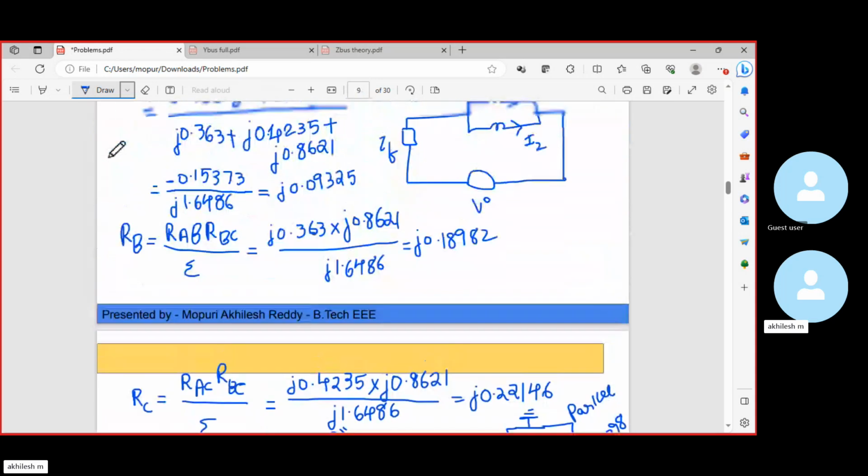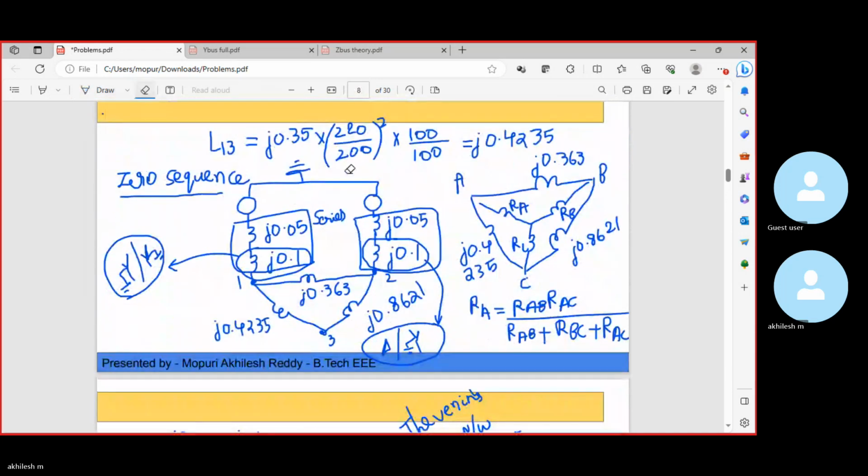So in this diagram, here there will be a break in the circuit. And this end is connected to the ground. So this is connected to the ground here. So when we are doing the equivalent circuit calculation, we will just remove this portion. This portion is not required. Why? Because there is an open circuit.